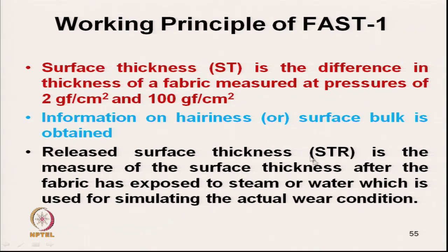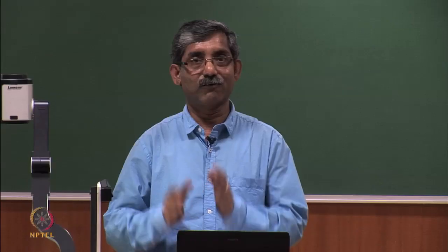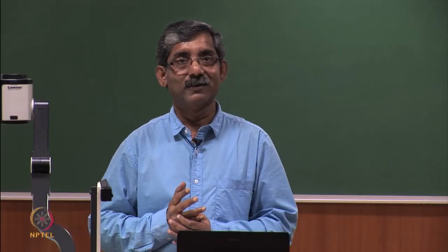If the released surface thickness is much more than the surface thickness, then it shows that after exposure to steam or water, which simulates the actual wear condition, the fabric is losing its finish; the finish is not permanent.